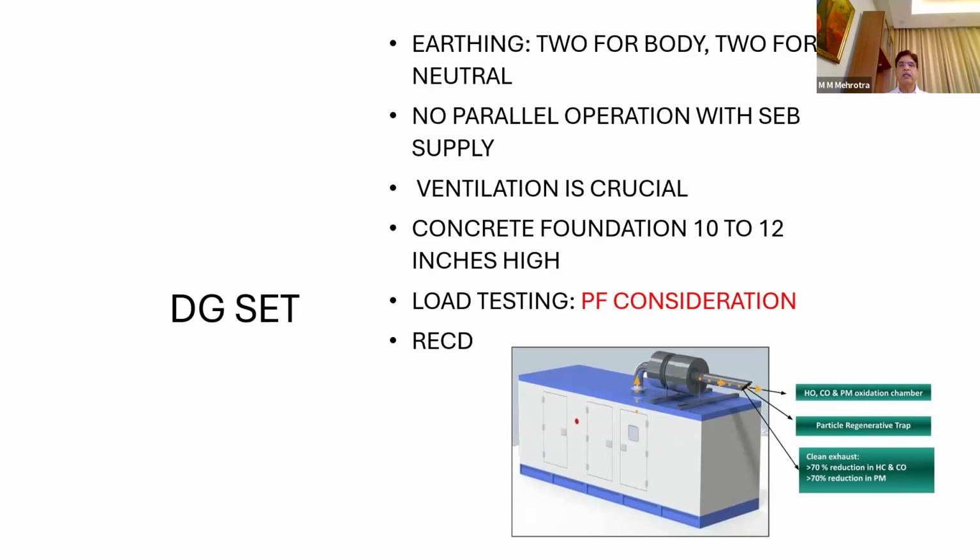Now this thing is put on a concrete foundation, a stable concrete foundation. Load testing is a little complicated. I'll leave it. RECD, these days this RECD is coming into discussion. Retrofit emission control device. As in the case of vehicles, you must have seen India pollution series, 4 number, 5 number, 6 number, like that. Similar pollution control norms have been put by the government, but generator technology will not change overnight.